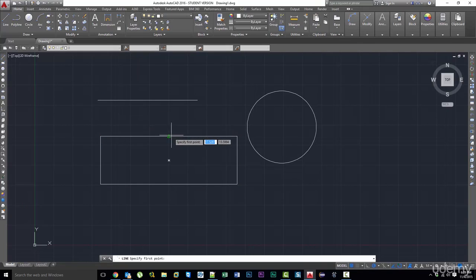We had to create a line from one edge, and then we had to use an extension from the snap point on the adjacent side, and we'd create that line. And then once we had a line that went into the center of that rectangle, then we could go ahead and use the endpoint of that line to create whatever additional features we wanted. So that was this extra step that was really kind of a pain in the butt, but now we've got this geometric center.